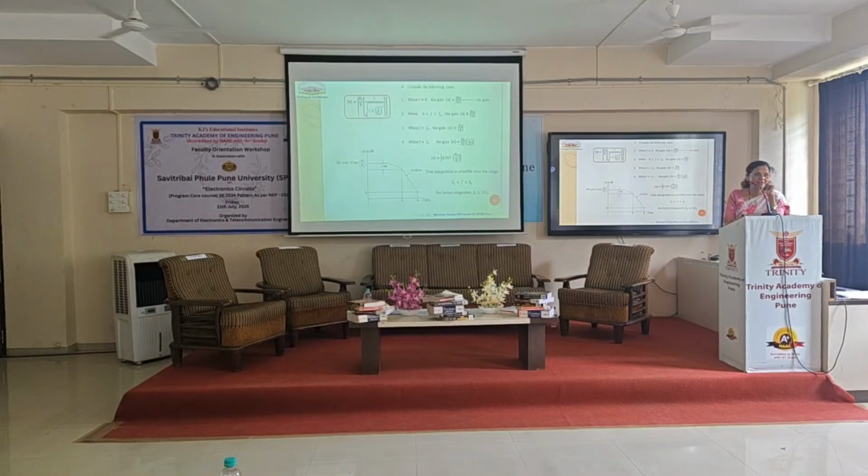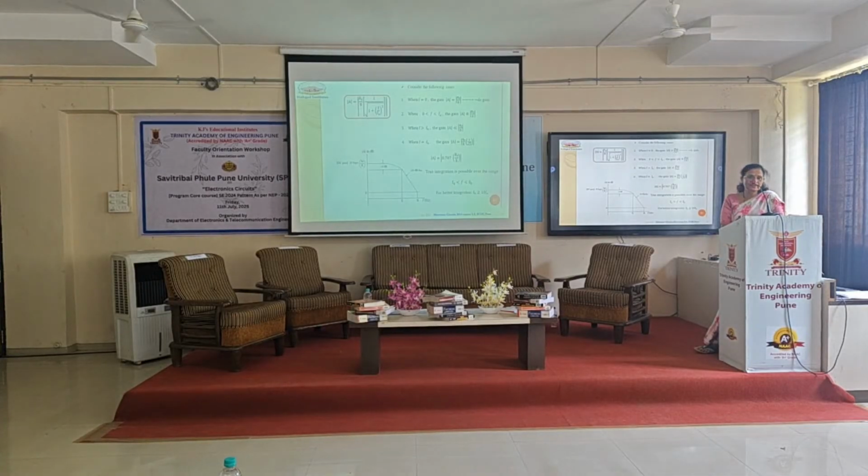We were explaining this concept based on poles and zeros, but the students do not have the concept of poles and zeros. That's why we are going for a simple way, due to the presence of RF. Based on the voltage gain equation, the response decreases by 3 dB, and that frequency is called the cutoff frequency. Now this is the response for the practical integrator.